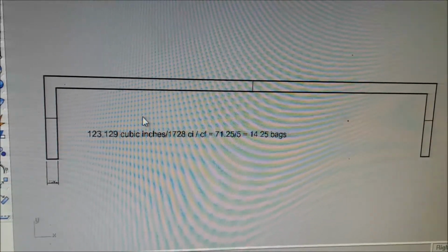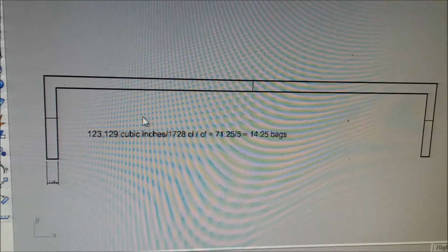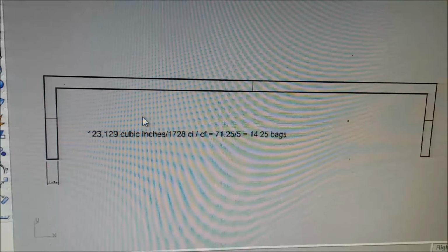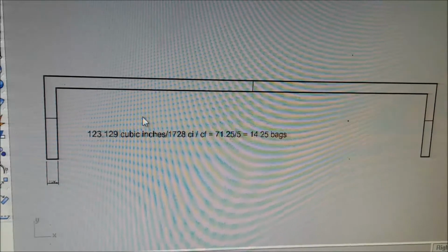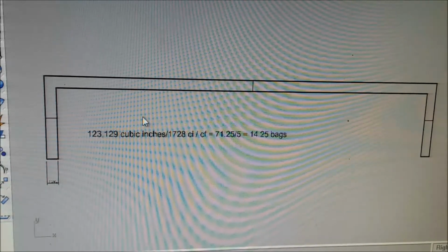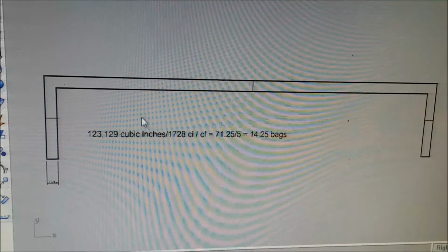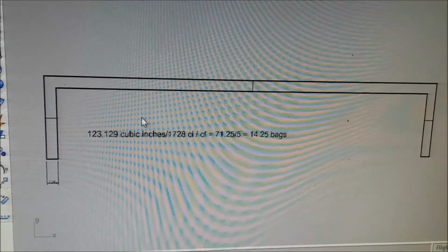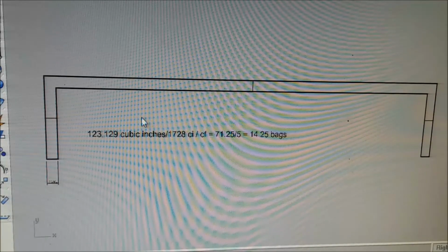And the site looks such a mess when you start with these piles of dirt, and it looks like a landfill. And then as we went around, we kept doing them in order so we could keep putting tie beams. And then while we were doing the outside ring of columns, we could take the mixer in and out any place we wanted, because the wall's 24 foot long, the mixer's 5 feet wide.